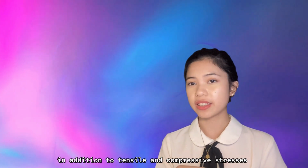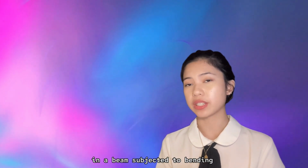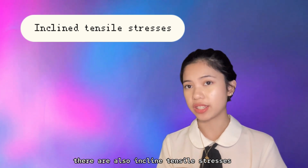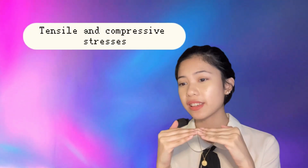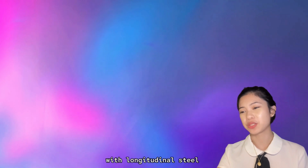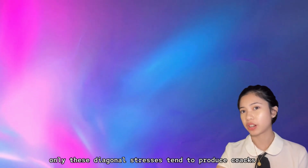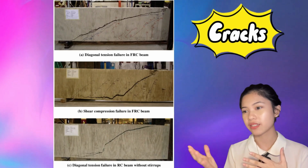In addition to tensile and compressive stresses in a beam subjected to bending, there are also inclined tensile stresses. So, in a beam, nagbe-bend siya, it's because of tensile and compressive stresses. If a concrete beam is reinforced with longitudinal steel only, these diagonal stresses tend to produce cracks. So eventually, nagproduce siya ng cracks.